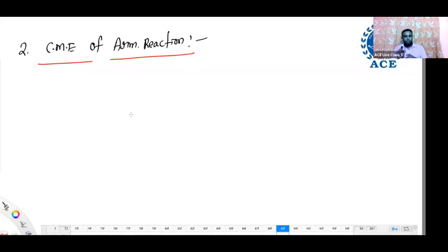If flux is 0, is there any EMF in the coil at that time? No EMF, because during the commutation process, every coil behaves as a short circuit. During that short circuit, if there is any voltage in the coil, current will flow. That current may sometimes cause heavy spark also. So there should not be any EMF at that time. EMF 0 means current also 0. Then you don't get any spark. That is a safe operation.